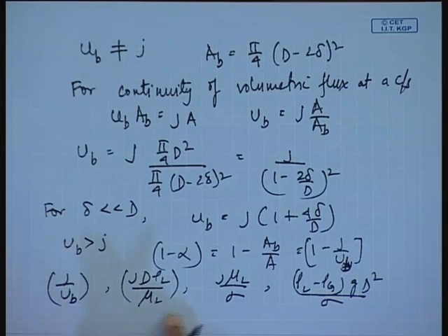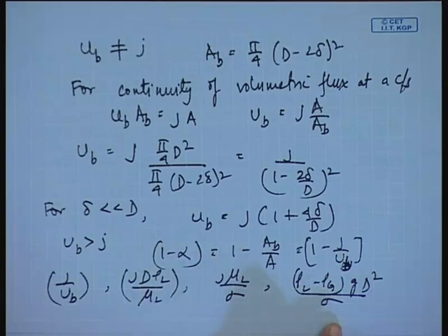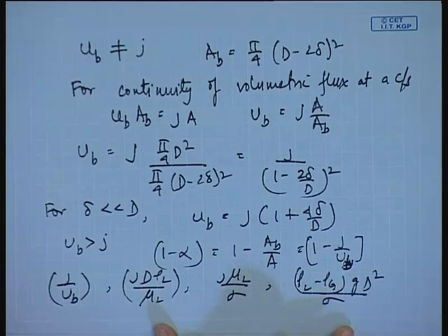If you notice these terms, you find that more or less these three terms correspond to the dimensionless groups which we had obtained for vertical slug flow. There also it was buoyancy by surface tension, buoyancy by viscosity, buoyancy by inertia. More or less these terms also correspond to an identical balance of forces which we had obtained for the vertical slug flow case as well.